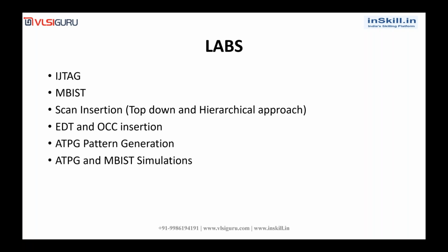And in simulations, we will be covering only no-timing simulations, because in order to do timing simulations, we require an SDF file, a standard delay format file, which is not available for the test cases in our institute.